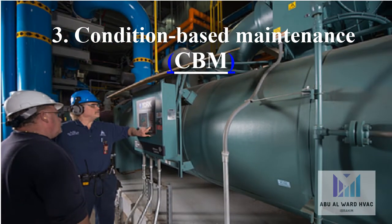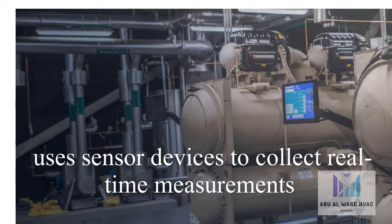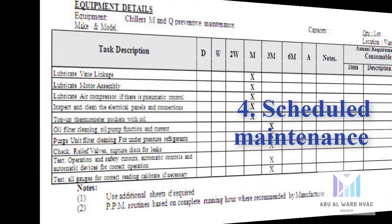The third type, condition-based maintenance. Condition-based maintenance, CBM, is the core of predictive maintenance, but on its own does not rely on technology to determine the condition of an asset like PDM does. CBM uses sensor devices to collect real-time measurements, i.e. pressure, temperature, or vibration, on a piece of equipment. CBM data allows maintenance personnel to perform maintenance at the exact moment it is needed, prior to failure.